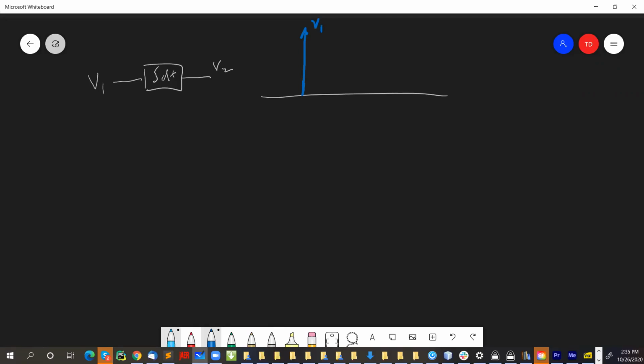So suddenly you put in a million volts into V1, but only for a nanosecond. It's like you're suddenly putting a bunch of charge on the input. What's going to be the output of the circuit? Well, if it's a perfect integrator, it'll just integrate up that charge that you put there and make an output. So the response to this delta function input is like a perfect integrator. It'll just tell you that the charge changed.